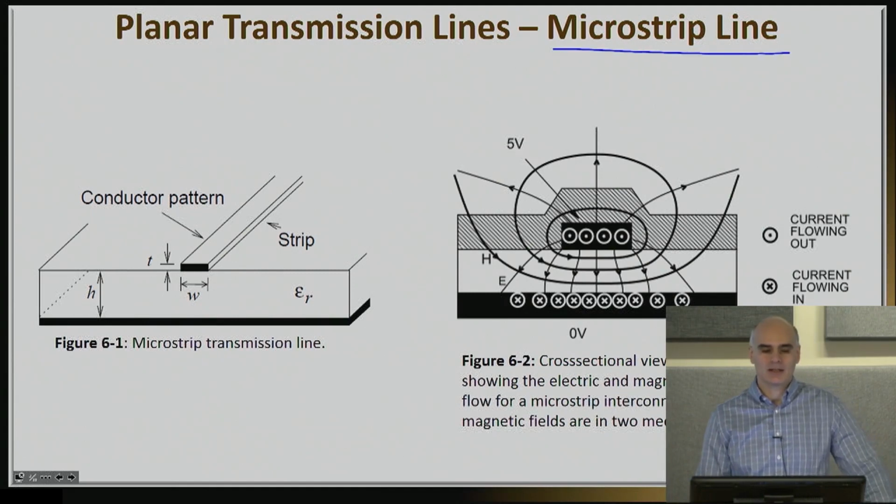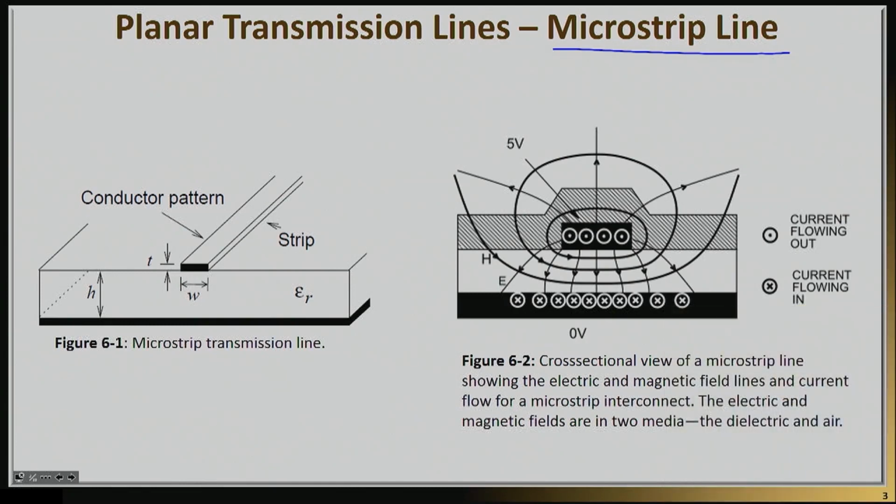This is the line that I briefly mentioned before, and I have actually put here its main schematic, its main geometry. So if you look at this, it's a very simple line. In fact, it's loved for its simplicity. It's literally just one strip on top of a ground plane. And that dielectric that you have below is basically the substrate that is essentially holding that strip.